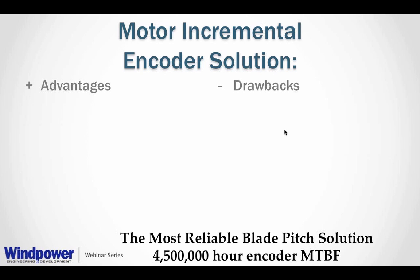So the disadvantage of the incremental encoders, you've got to have some way of finding the home position or going to the home position. And vendors have accomplished this in a number of different ways. Some vendors have DC motors where if they lose the home position, they just engage the battery system and run the blade pitch till they go home. Others use more sophisticated methods to figure out where they are if they lose the feedback solution.